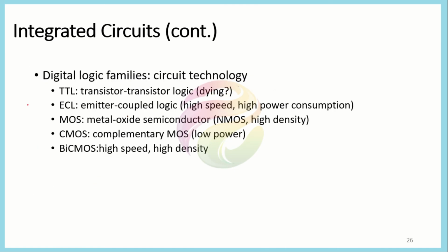There are a few standards that are used in the circuitry. The basic one, or the starting one of digital logic, was the TTL logic, the transistor-transistor logic. The other one is the ECL, and generally the ECL is preferred when we need very high speed computation. And then we had a metal oxide semiconductor technology, which is called the MOS, and after that we had the complementary metal oxide semiconductor, CMOS. Currently most of the ICs, the gates, or the actual transistors that are implemented are based on this CMOS technology. You have seen that the advantage of CMOS and its derivatives like BiCMOS is that it requires very little area to represent a very large number of gates. You can embed millions of gates in a single IC chip very easily these days.